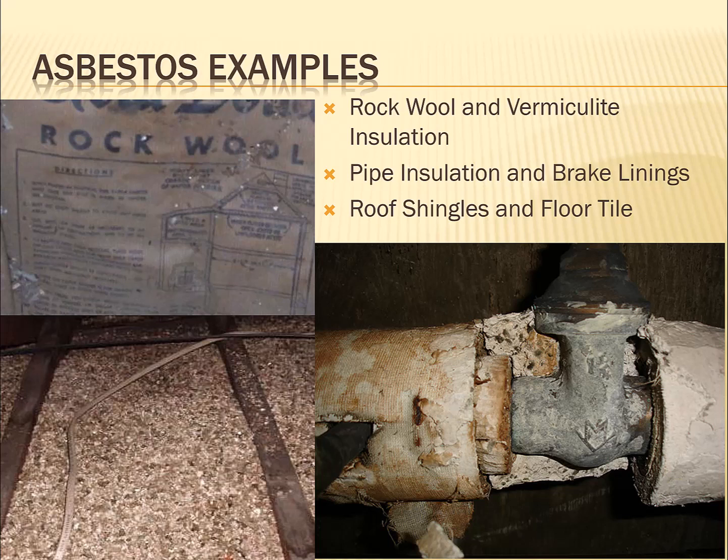So you want to make sure that you're not around this stuff in a way where it's loose and airborne. In fact, when we're doing an asbestos cleanup, half the battle is getting it wet so that it's not airborne, or containing it inside containers as you remove it. Sometimes if they had to remove insulation from just this area of pipe so they could change this valve, they would wrap it all in a big bunch of plastic to seal it up.